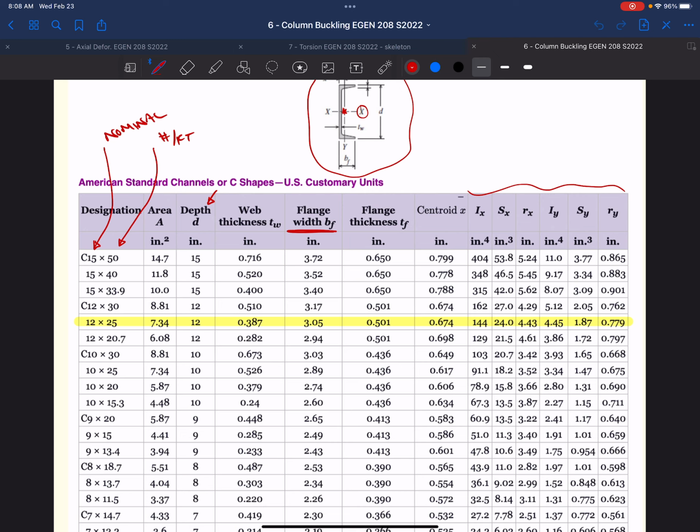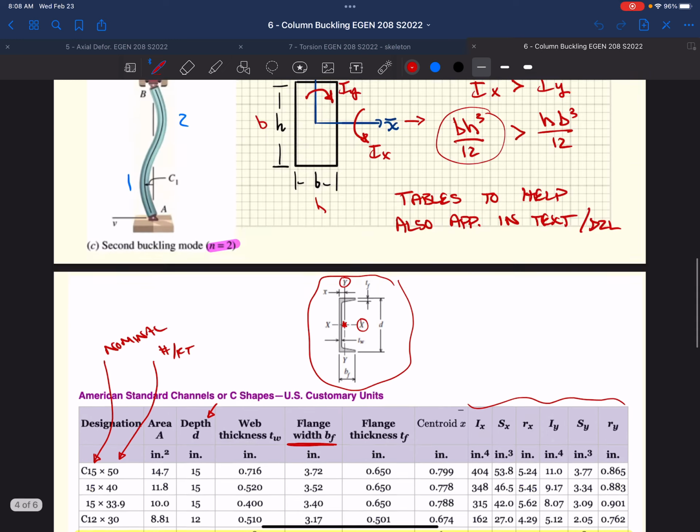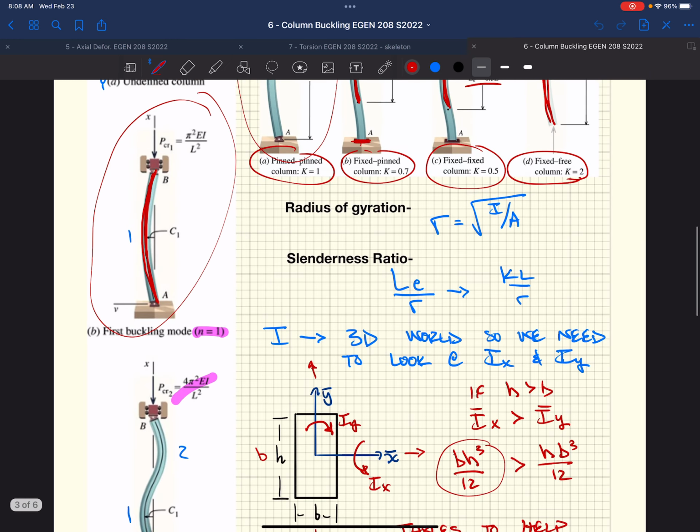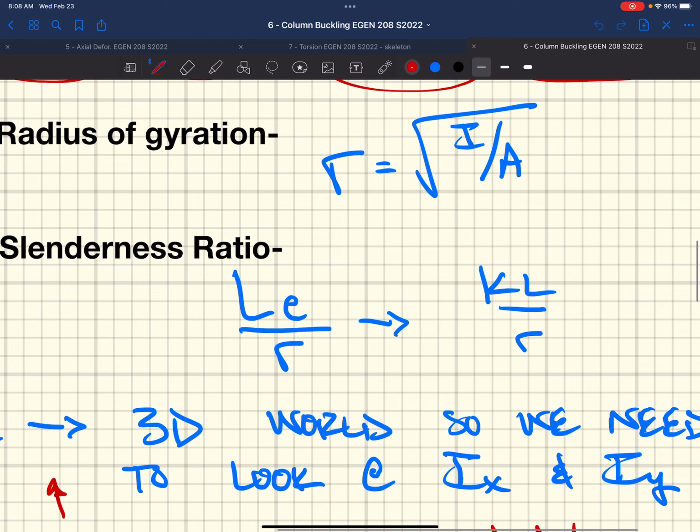And then in the strong direction, maybe we won't put anything perpendicular to that. So we would tie off to the walls on both sides to essentially keep this column from being able to move side to side halfway up. And so then that affects what we do with respect to our effective length, KL over R, that changes from the weak axis to the strong axis, yeah.